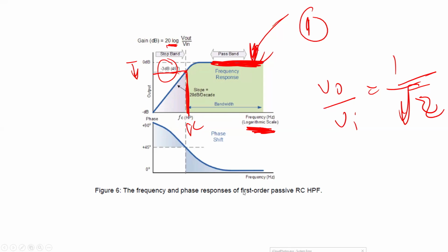In the coming lab, I'm going to ask you to just focus on 3 values. At very small frequencies, you should see a phase shift of positive 90. Here, you have to see a phase shift of positive 45. And then here, you should see a phase shift of 0. Please, guys, you need to understand what I mean by phase shift. When it is 0, that means they are at the same time. There is no leading or lagging.